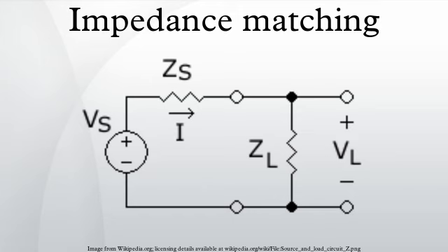The output stage in common drain or common collector semiconductor-based end stages with MOSFETs or power transistors has a very low output impedance. If they are properly balanced, there is no need for a transformer or a large electrolytic capacitor to separate AC from DC current.